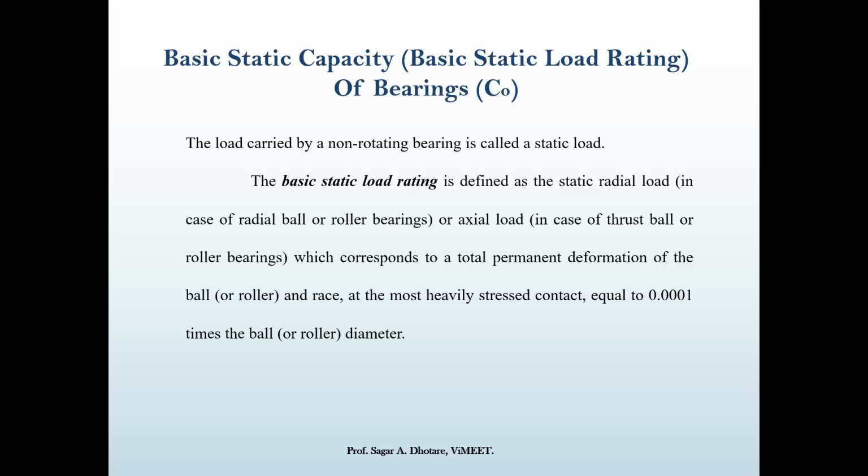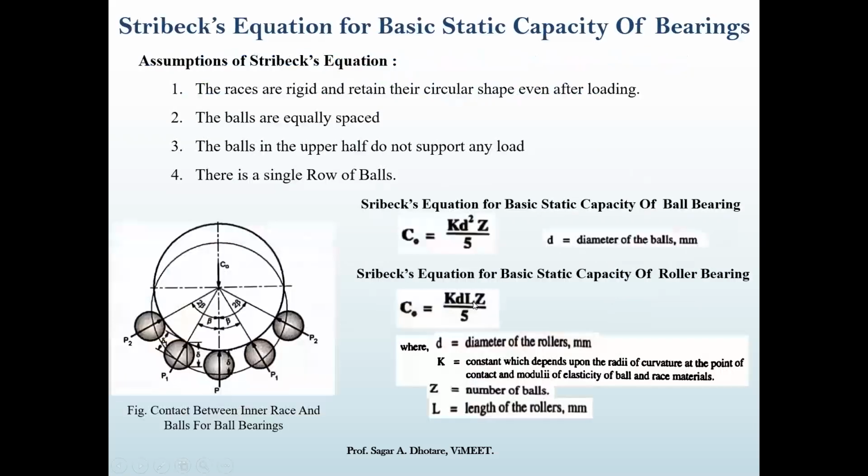Okay, now to find out the basic capacity, there is one equation provided, that is Stribeck's equation. It can provide the value of basic static capacity. Okay, we should know how much basic static capacity is required, and only then can we choose the standard value of the bearing.